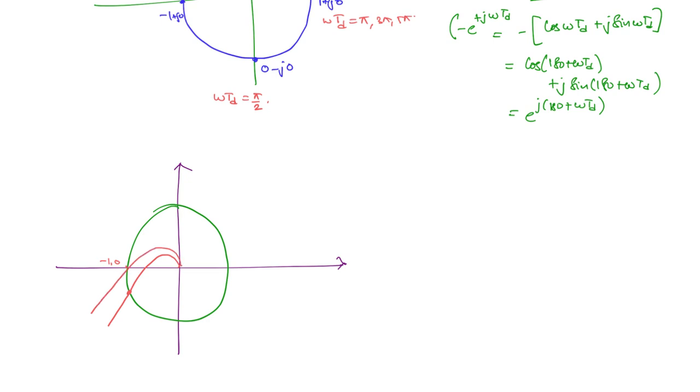When it is intersecting the critical trajectory at the real axis itself, then it is called at the verge of instability, right? So you can write here, this is stable, this is verge of instability. Okay. Then what about when the intersection is beyond the real axis, that means in the second quadrant, then it is called as an unstable system. Okay, so this is how you decide the stability based on critical trajectory.